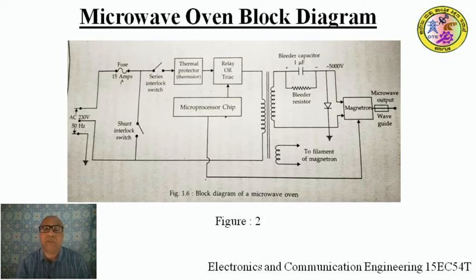The bleeder capacitor should always be discharged before touching anything inside when the cover is removed. So one thing is for sure, you should not be opening your microwave oven in your home. You should call the experts, because this capacitor, when it is charged, it is harmful. So we need to discharge it first before touching anything inside when the cover is removed. This is only for the purpose of the technicians, not for the home use. The high value bleeder resistor is slow to discharge.